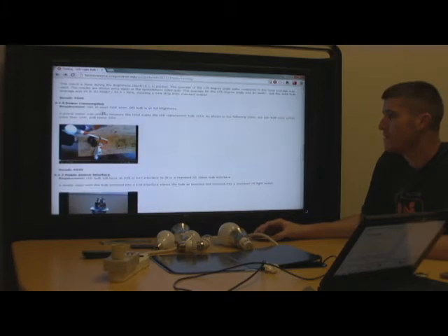Our sixth engineering requirement was that the bulb will use at most 35 watts. We hooked up a regular power meter and plugged in the bulb at full brightness. It ran around 12 watts, anywhere between 11.8 and 12.2, so it definitely met the 35-watt max requirement.